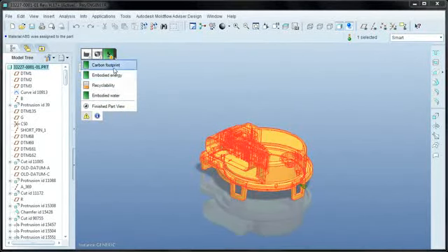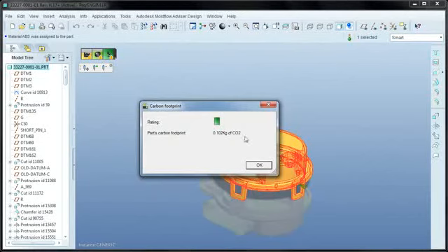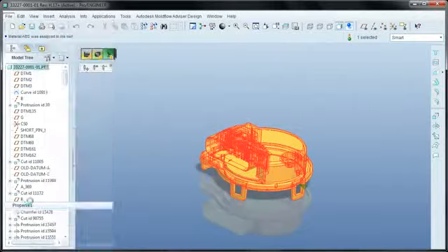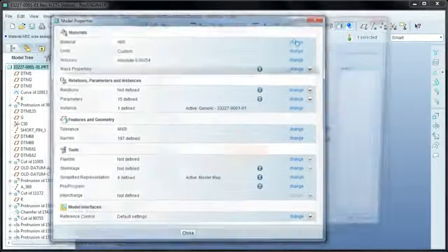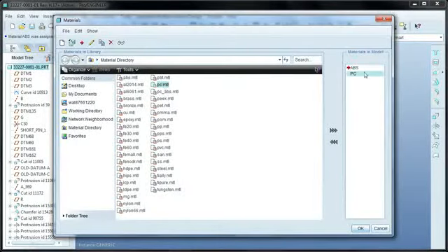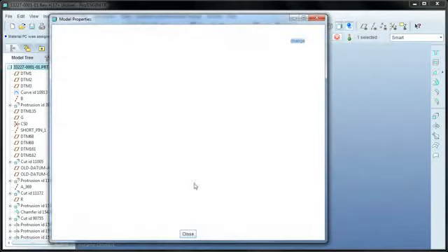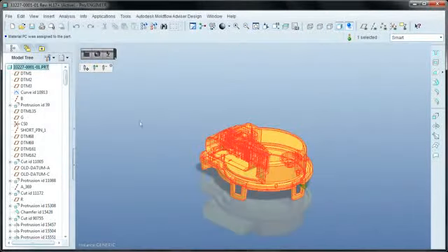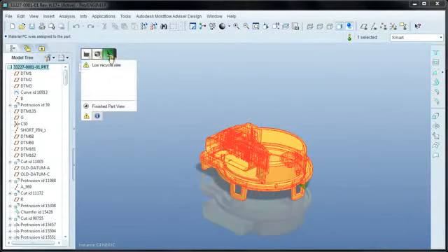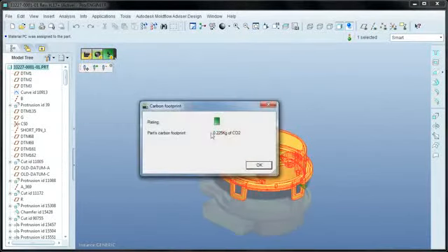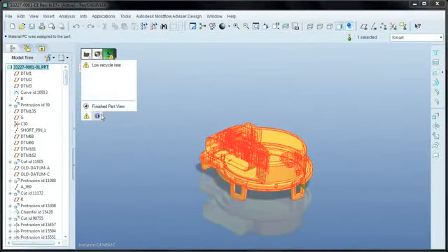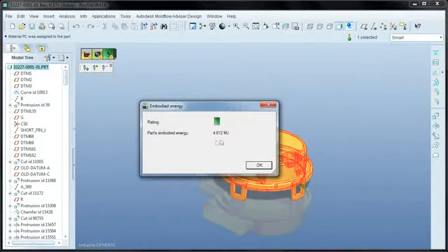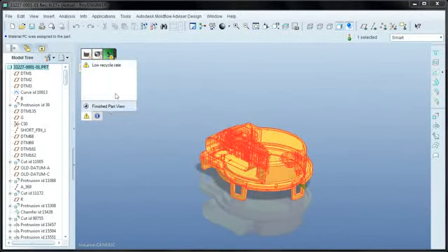Now the final indicator is plastic material impact, which has four factors. Carbon footprint calculates how many kilograms of CO2 are produced when making the necessary amount of raw material for the part. For example, if the material is changed from ABS to polycarbonate, the amount of carbon produced per part more than doubles. Embodied energy is the next result, and this calculates the amount of energy required to manufacture the part, which again is mostly impacted by the selected material.